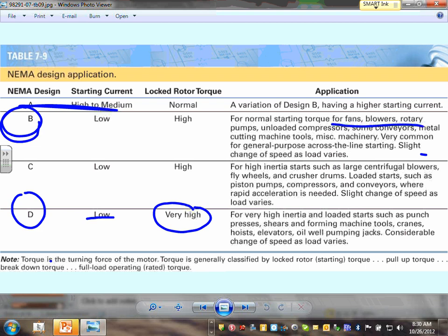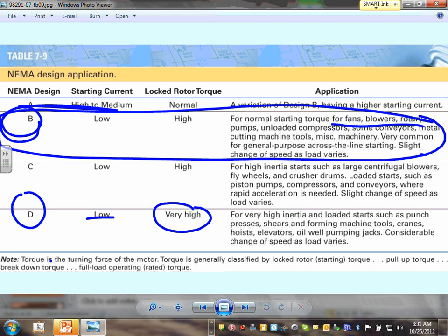So long story short, guys, they size the motors to be able to handle different types of loads. The motor that is used to crush rocks is different than the motor that you use to run a fan. Do you understand that? The whole idea is, do you need torque? If you need more torque, you have to have a special type of motor. The motor that you use to hold a process, just hold it tight, that's a torque motor. They design them just not to rotate, just to torque. So they have different types of motors. You guys, almost always, you are right in here. Us in construction, we are almost always in design B motors.